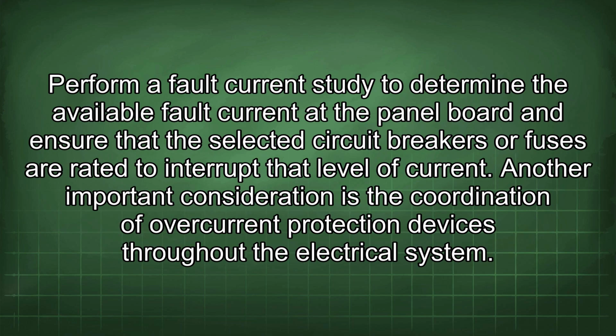Perform a fault current study to determine the available fault current at the panel board and ensure that the selected circuit breakers or fuses are rated to interrupt that level of current. Another important consideration is the coordination of overcurrent protection devices throughout the electrical system.